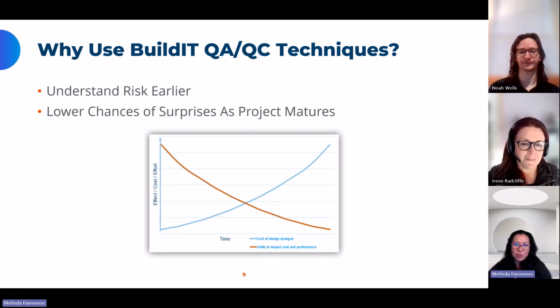Yeah, that reminds me of one of the customers I was working with recently, where we had to scan concrete floor panels. They had a modular building, and they basically created floors for the hospitals, making modules of the hospital floors for the bathrooms. They needed to find out the slopes and the surface deviation against CAD. So we were able to install the scanner about 10 feet high. It would scan and basically inspect the floors. It would then give you a deviation straight away, and also find out the slopes of the floors that they needed for the drains. And all that was done in 1 minute.